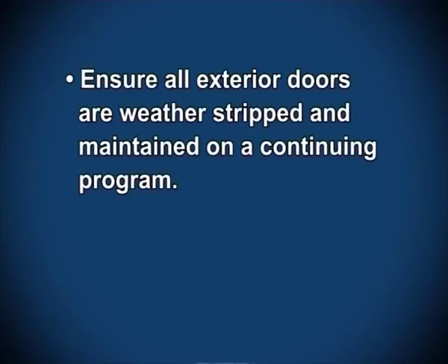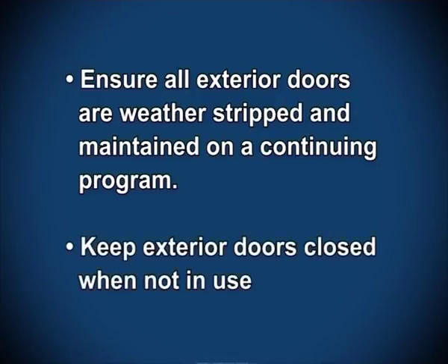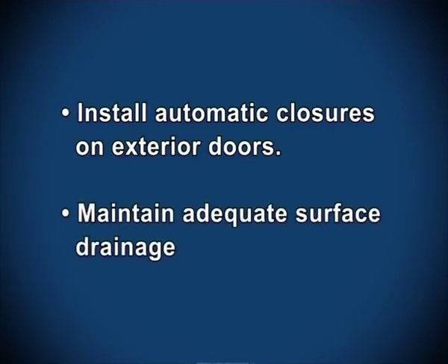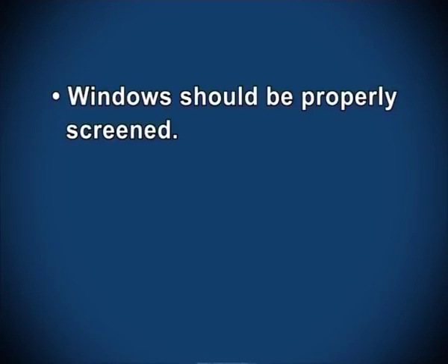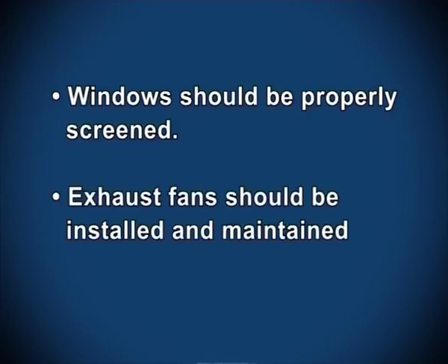Ensure all exterior doors are weather stripped and maintained on a continuing program. Keep exterior doors closed when not in use. Install automatic closers on exterior doors. Maintain adequate surface drainage. Windows should be properly screened. Exhaust fans should be installed and maintained.